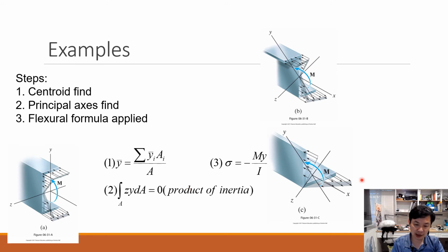And here is another case, we call it the L-shape cross-section. For this kind of L-shaped beam, the symmetric line would be one axis, along the 45 degrees. And this gives you another principal axis, perpendicular to it. Then we still can neglect the product term, but finding our centroid is a little bit painful because you don't have symmetry along any direction. You need to determine that one by one.